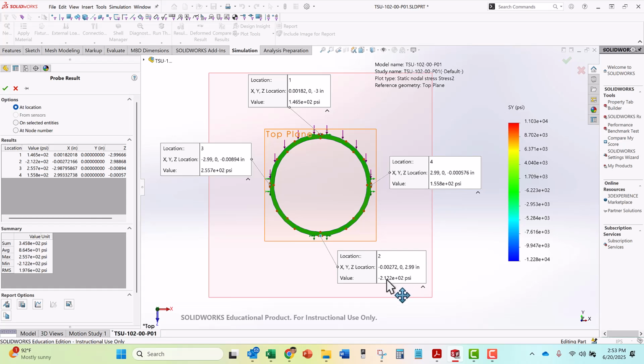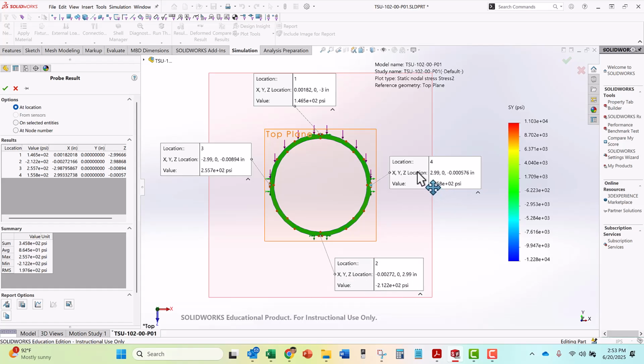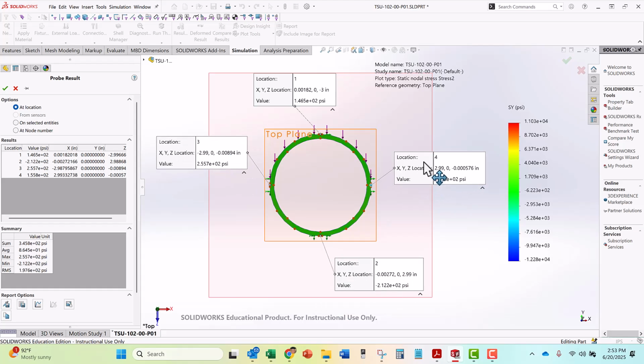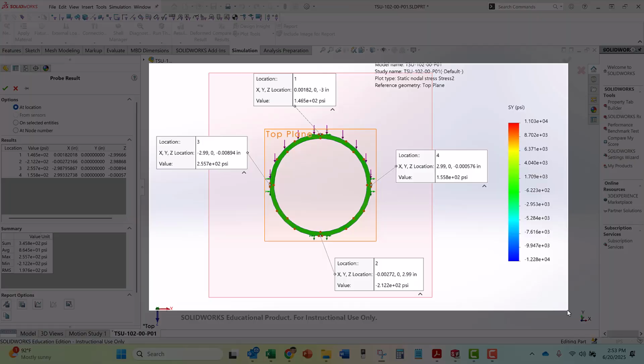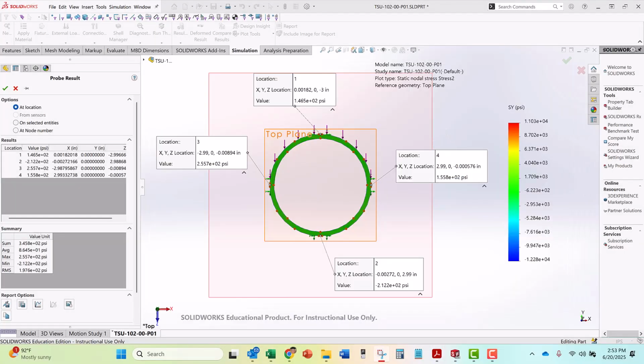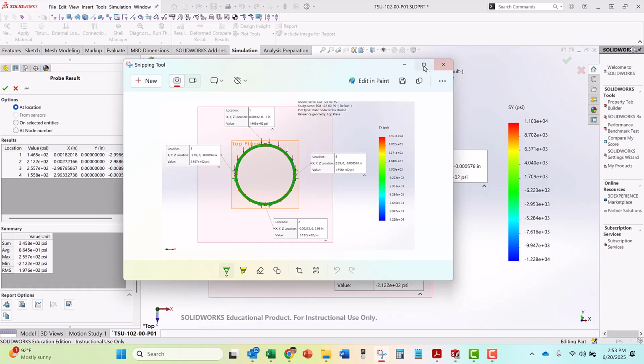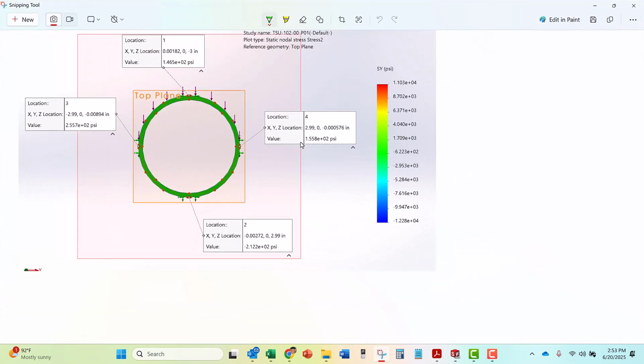on the Y face due to that vertical normal force and due to the moments created by that wind load. So you'll check these values here for these solutions I've got here, and you're going to compare those against the values you got for sigma Y at point A, which is this one, point B, this was point C over here, and this is point D. So you'll do a screenshot of this to keep for your records, and also email me so I can be assured your numbers on your simulation match your numbers that you calculated on the spreadsheet. And this is how you'll earn credit for doing the simulation for Project 1.